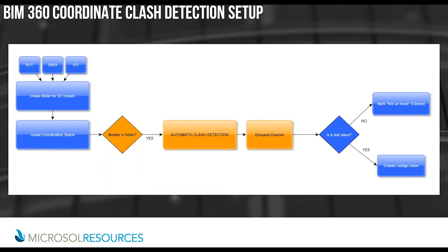In my experience thus far, it can take about 15 to 20 minutes to clash larger models. So it's not an instantaneous clash report, but if you want to go grab a coffee, or if you want to just pick everything up in the morning, so let it go overnight, you can do that, and when you return, all of your clashes will be grouped and organized and ready for review.